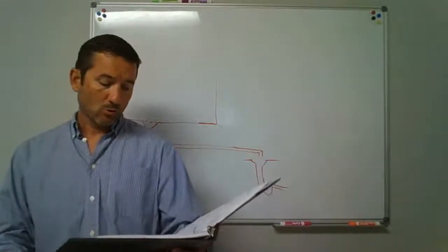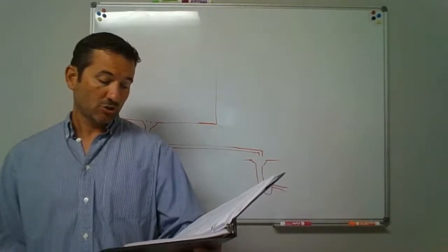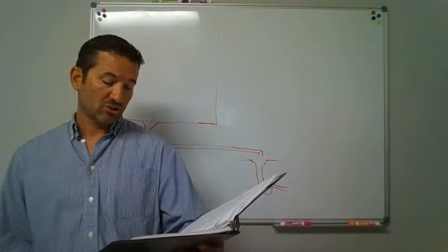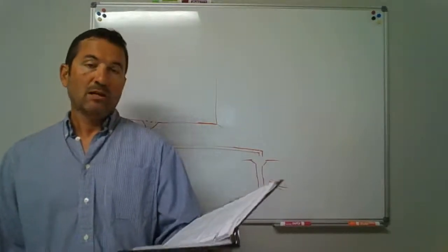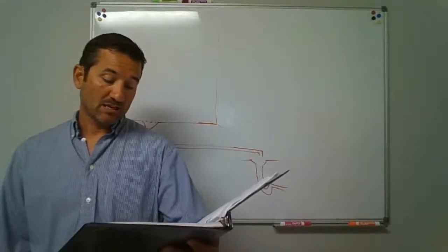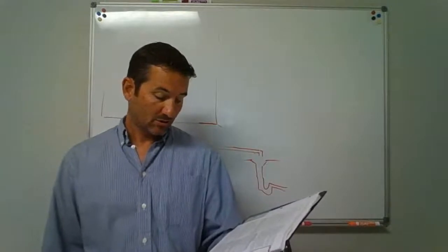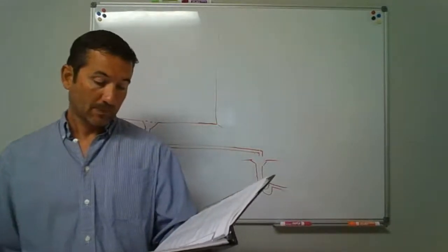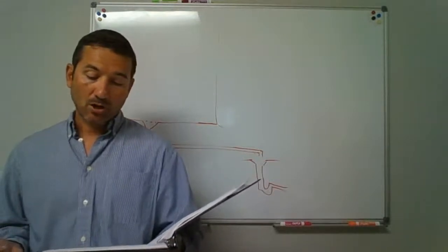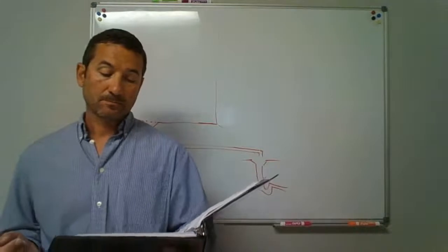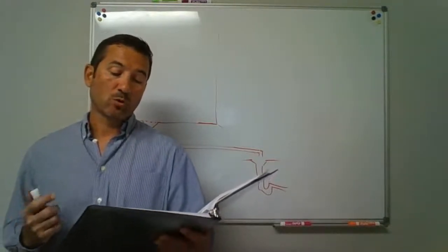All right, what else have we got? Potable clear water waste, where devices and equipment such as sterilizers and relief valves discharge potable water to the building drainage system. The discharge shall be through an indirect waste pipe by means of an air gap. It allows drinking fountains to be connected directly or indirectly to the drainage system. Okay, then it talks about swimming pools, non-potable clear water waste. Let's see, domestic washing machines. Let's look at that one, 802.1.6.